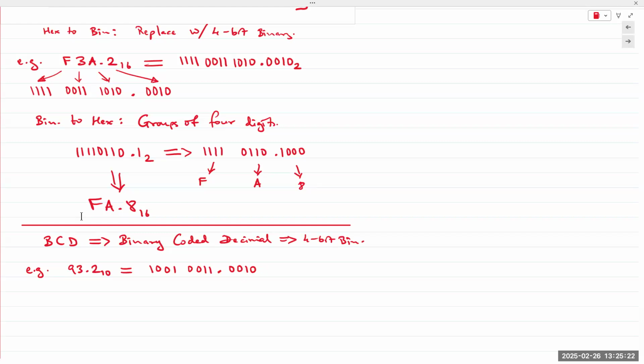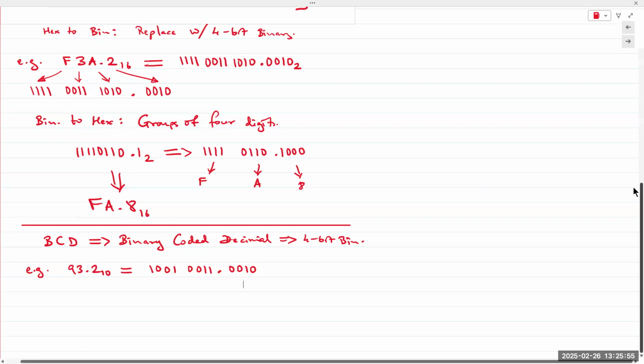That would be binary coded decimal. So in lab 7, we take our asynchronous counter from lab 6, and we feed the output of that counter into a BCD, binary coded decimal, to decimal converter. So we take the binary output and convert it into a 7-segment display decoder. And that's binary coded decimal. All right, any other questions? All good?